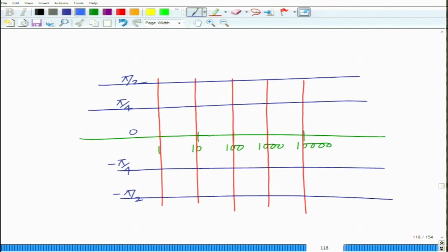At much less than 100, let us say approximately till 10, it is 0. At 100, it is pi by 4, much greater than 100, the phase is basically pi by 2. So, it rises from 0 to pi by 2. At 100, this is the corner frequency, this is equal to pi by 4, and the actual phase plot will look something like the following. It will look something like this. This is the Bode plot for the phase.